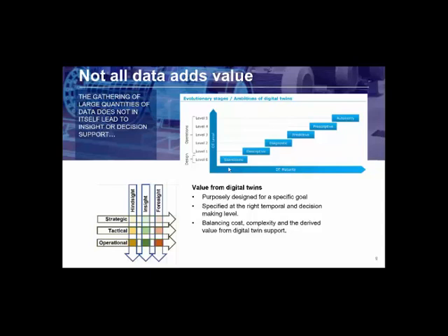Also, many systems today have a monitoring capability when it comes to vibration monitoring and modeling. That means that from real-time data, we are able to get some descriptive metrics about a system's response. And maybe with basic analytics, we can augment that to give diagnostic value, for instance in gearbox monitoring or the monitoring of bearing failure.